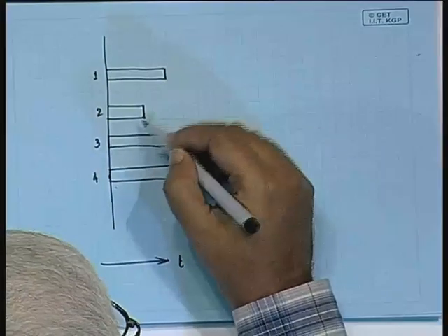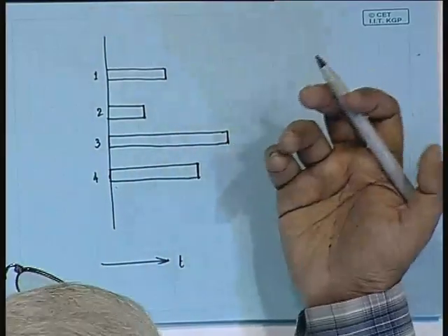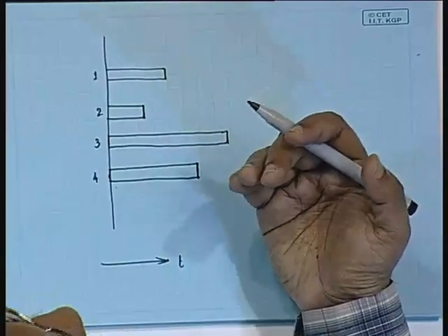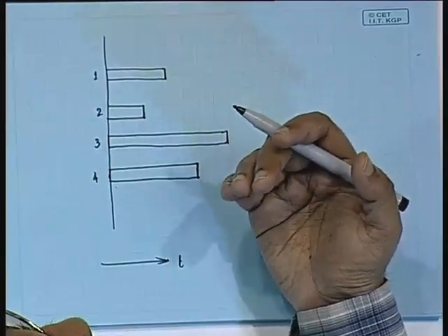One of them may be using G.728, another may be using G.729. Their bit rates could be different, and not only that, the amount of compression can vary from one frame to the next, and that is why there is no guarantee that, in fact in general it will never happen that all the channels will complete their collection of one audio frame at the same time simultaneously.